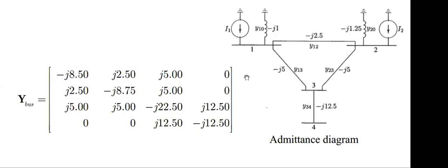Then from that admittance diagram, we have extracted the nodal equation. From that nodal equation, we have rearranged it in terms of the coefficient matrix Y, capital Y, right? When we have all the capital Y in our hand, we can extract that to generate the Y bus. That's the ultimate target. Okay. This Y bus is actually required for our other steps or next step purpose.